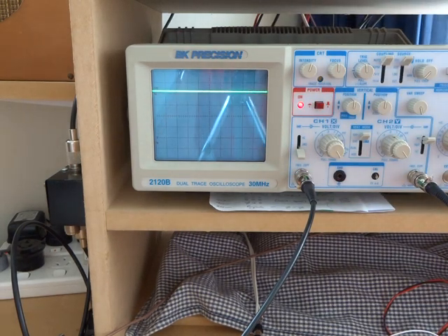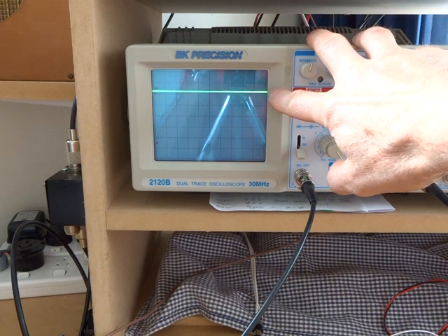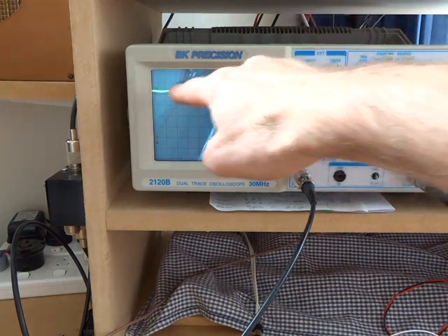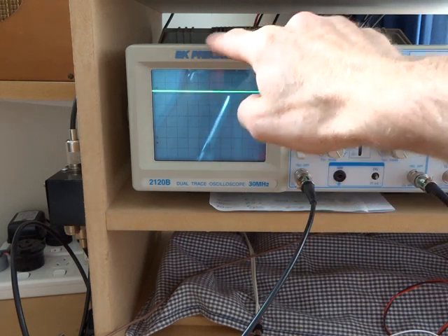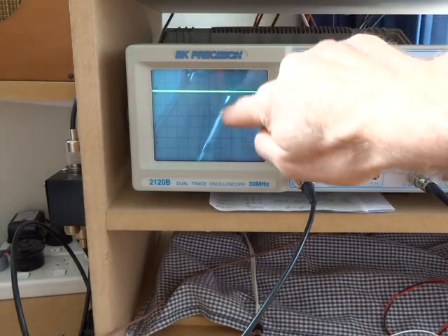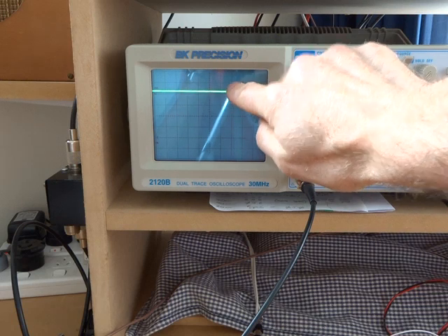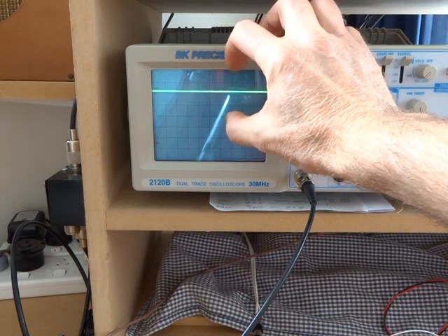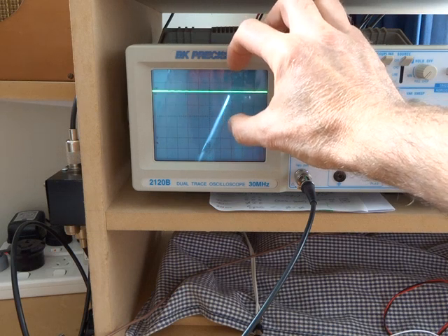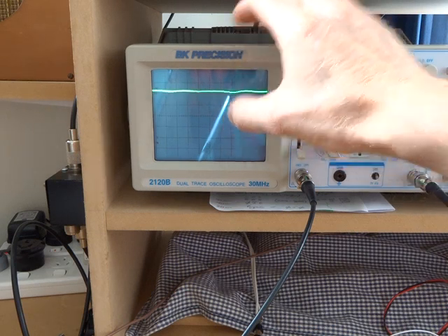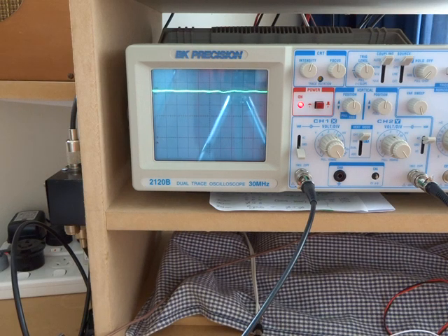And what I can see straight away, which is not right, is my understanding is that to get 100% modulation, that DC level should be varying down to 0 and up to 2 times VCC, in other words, essentially 2 divisions. And I'm definitely not getting that. So my modulation depth, even though I'm picking up quite happily on the SDR sharp and the AM receiver, is certainly not anywhere near where it needs to be.